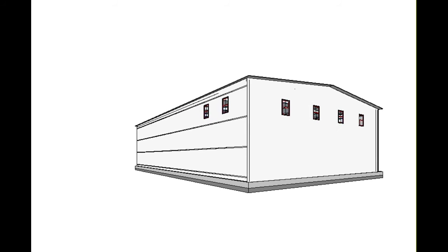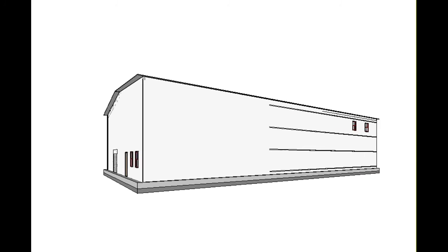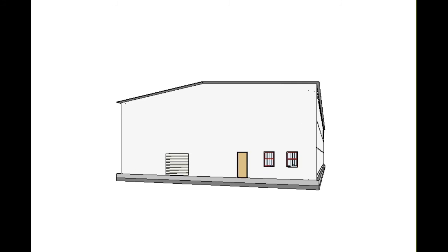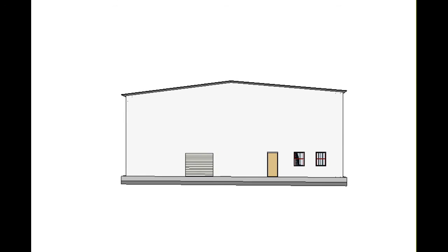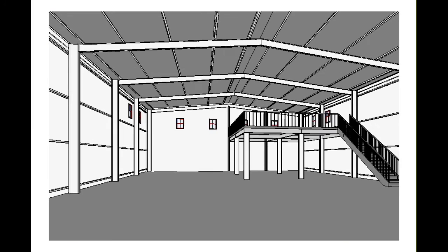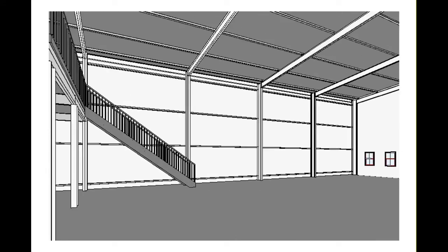As we begin to rotate around the structure, we see that the windows are around and above the mezzanine to provide the workspace with natural light where the office is usually located. The mezzanine is 4 meters above the ground level, which provides it with sufficient working room under and around. The mezzanine is also supported by 4 columns and tied to the surrounding portal frame to give it the structure it needs to hold the weight that will be experienced on it.